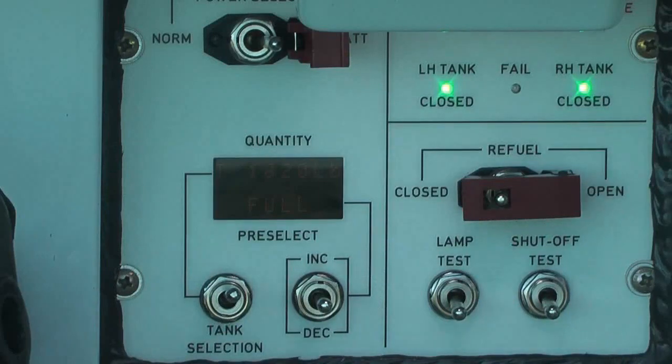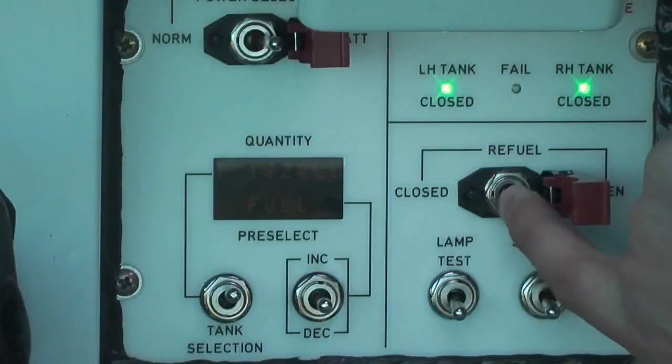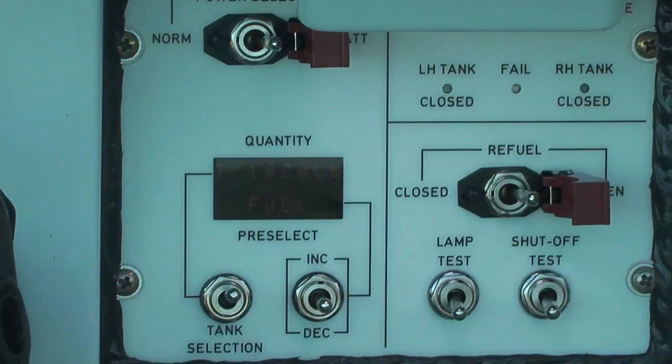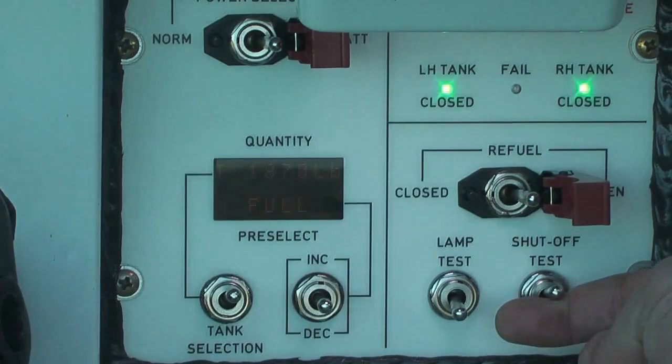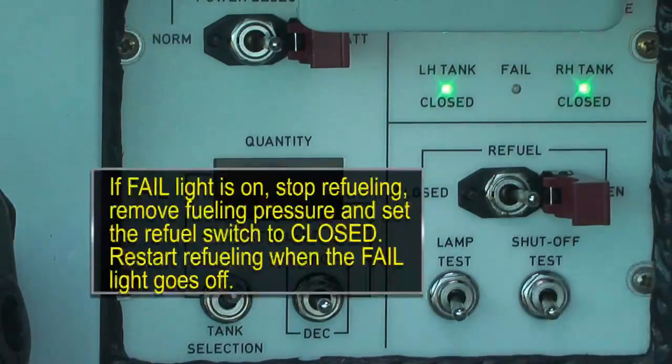Set the refuel switch to the open position and make sure the left tank and right tank indicator lights go off. Actuate and hold the shut-off test switch up and observe the left tank and right tank lights on and the fail light off.